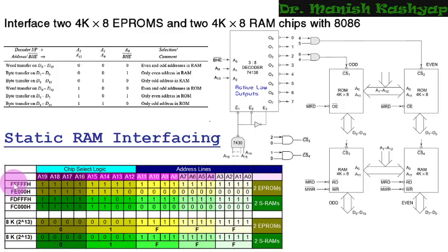This is the last address, 5 times F in 1 megabyte location, right? Now, if you want to go to locations 8K before that, because you have two such chips, you will be subtracting 8K from that, right? And 8K, if you see, is 2 raised to the power of 13. So here I have written the binary representation of that number. 13 bits.